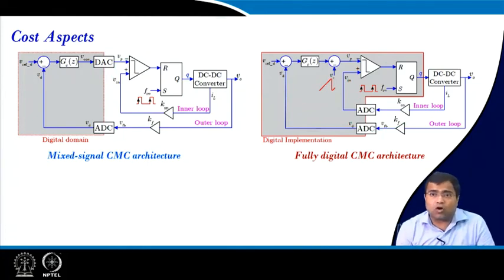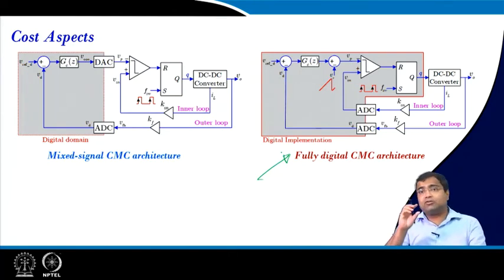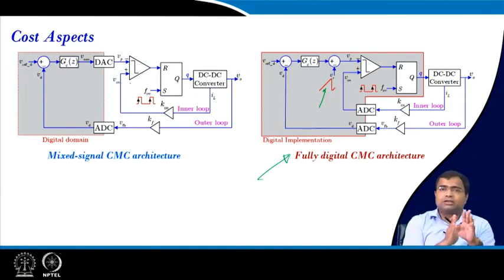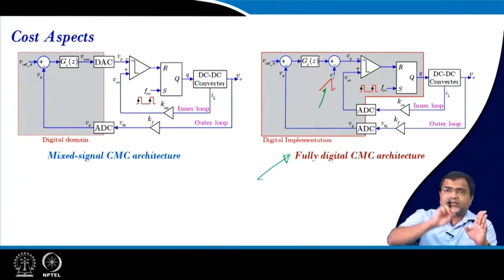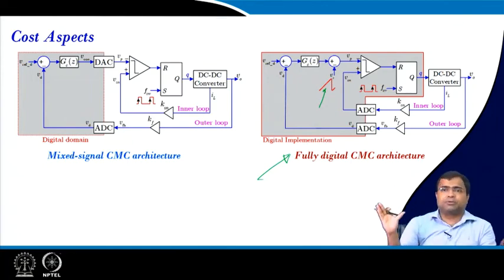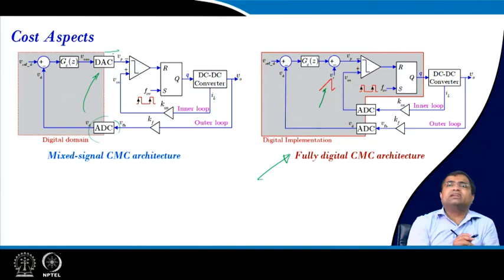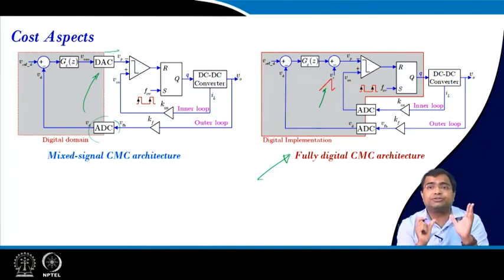If you talk about cost, you can cut down the cost in this technique, but it also imposes a challenge because the resolution of this emulated ramp will create a duty ratio limit which is not there in analog control. Analog control is just an analog signal, so there is no resolution problem. The resolution will only come from the ADC as well as the DAC. So it will only give a resolution of the peak current difference, and that will impose some duty ratio resolution.